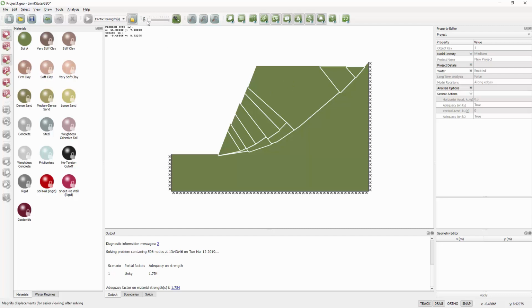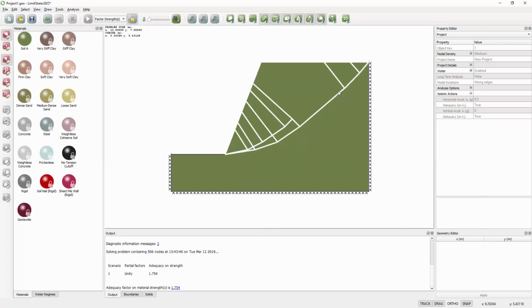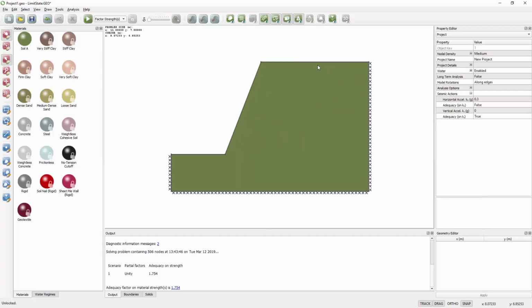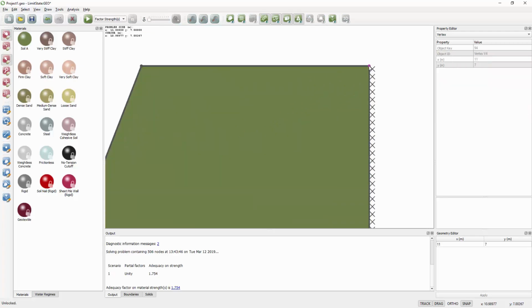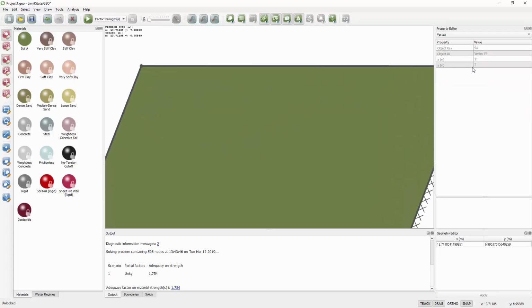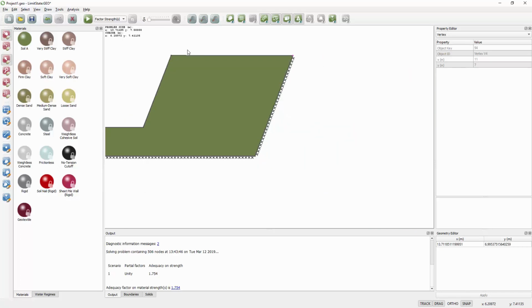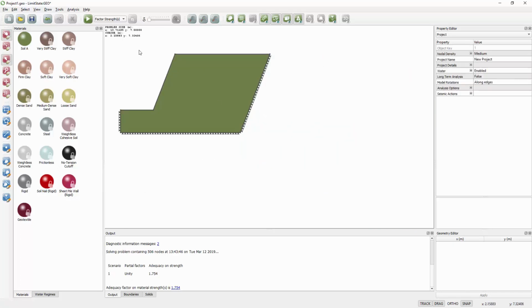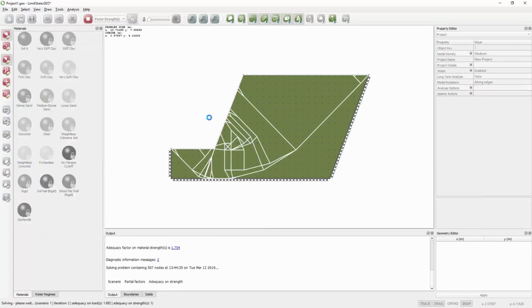And while we've got this up here, one thing you can see is that this line intersects the top of the boundary. Now this boundary is in essence artificial, and so unless it actually represents a wall of rock or something, it's too far out and it's affecting the result. So if we see that, we ought to move it back. I'm just going to do that quite crudely by dragging and dropping the geometry. And then I solve again.